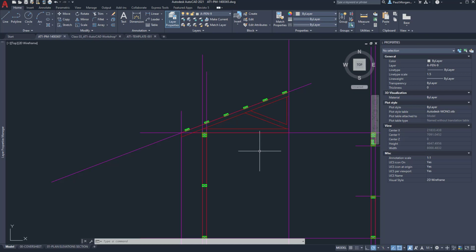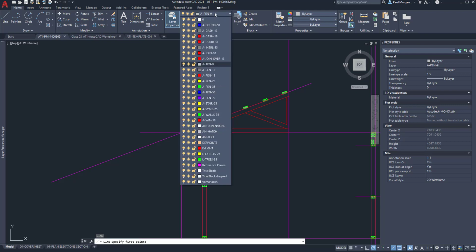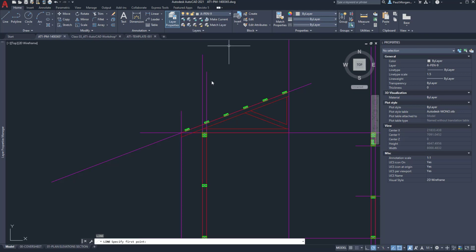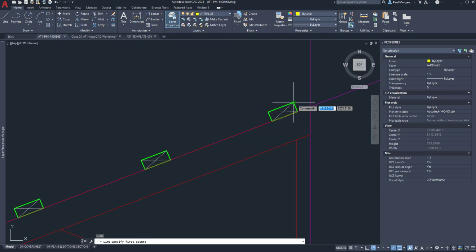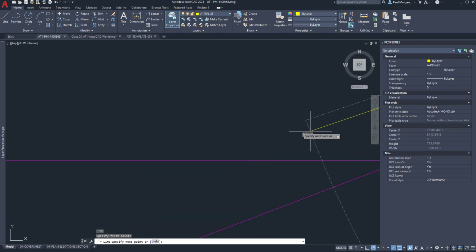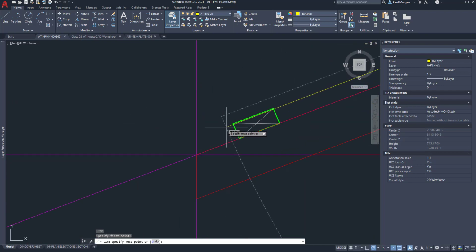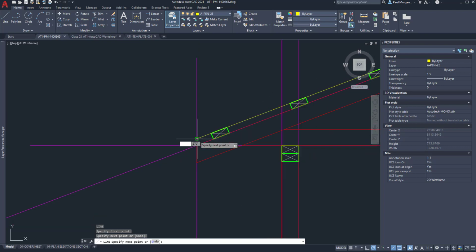The next one is our roof sheet itself. Now, at this point, we're still doing a section, so we don't need ultimate amount of detail. So we're just going to use a 0.25 line. So I'm going to go my line tool. I'm going to go pen 0.25, and I'm just going to go from here down to about here, and then hover my mouse over and then click.